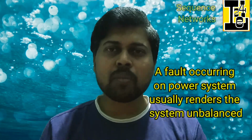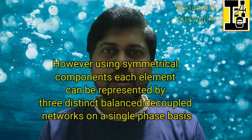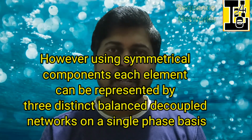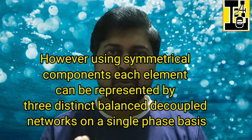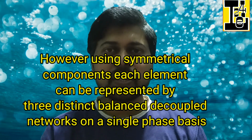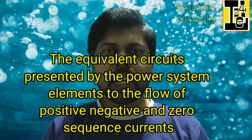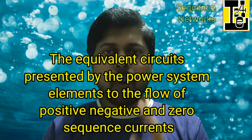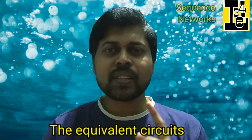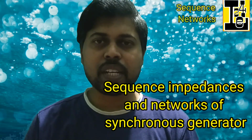A fault occurring on the power system usually renders the system unbalanced. However, using symmetrical components, each element can be represented by three distinct balanced decoupled networks on a single phase basis. This makes the analysis simpler. In this video, you will be studying the equivalent circuits presented by the power system elements to the flow of positive, negative and zero sequence currents. Let me start with the synchronous impedances and networks of a synchronous generator.